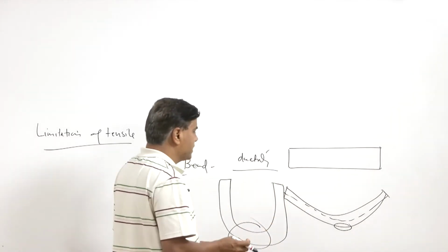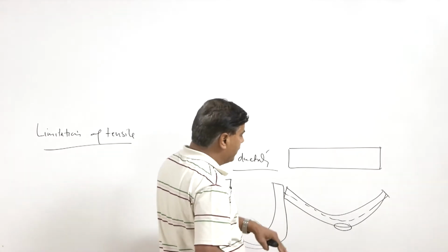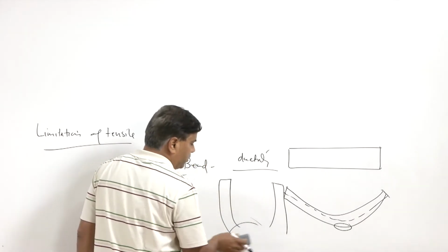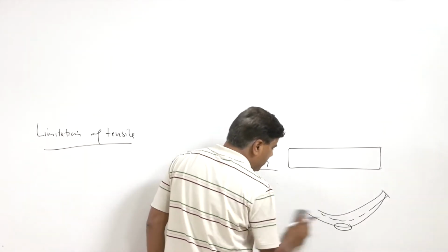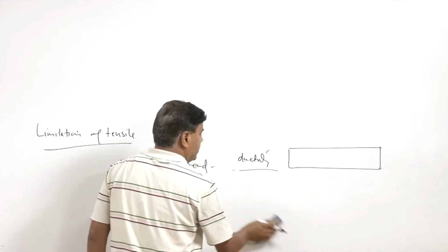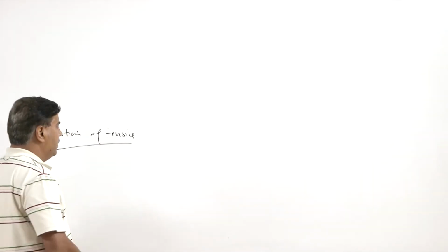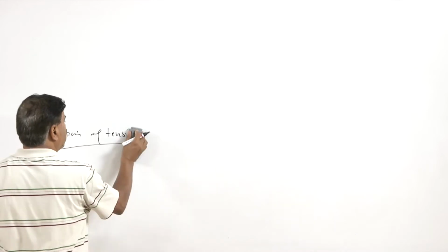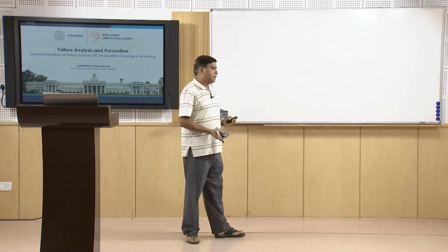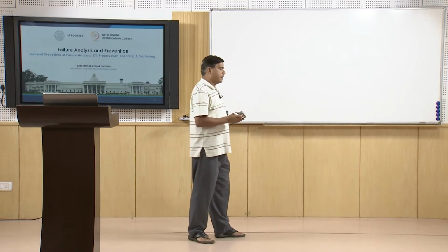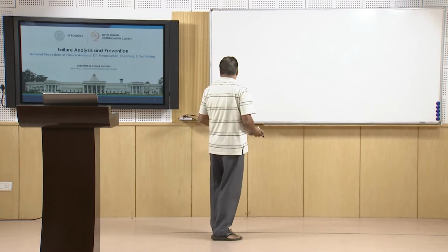So, this difference indicates the extent up to which the outer layer of the material will be elongating prior to the nucleation and the growth of a crack on the outer surface. So, maybe the ductility can indicate the better resistance for nucleation of the cracks and their subsequent growth. So, maybe it will be more useful to conduct the bend test on the failed components, so that we can see really the extent up to which material can be deformed plastically prior to the nucleation of the cracks or appearance of the crack on the surface which is being elongated.